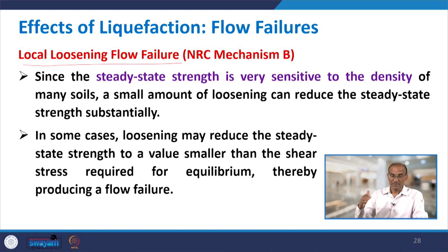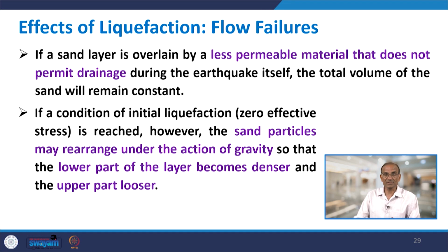So, this loosening of the soil, not only is there a change in stresses, but it also reduces the steady state strength, and once the steady state strength itself is reduced, then naturally even if the stresses are low, there will be chances of liquefaction.